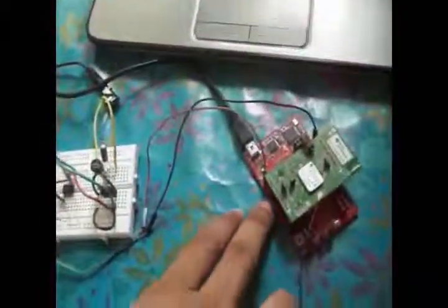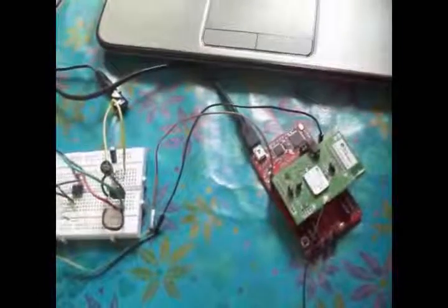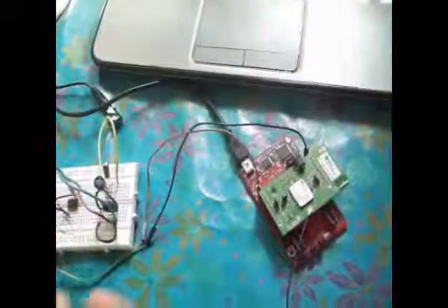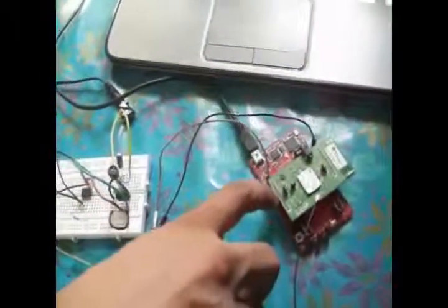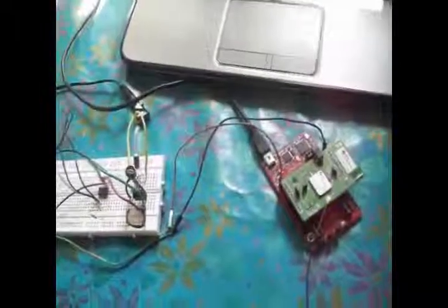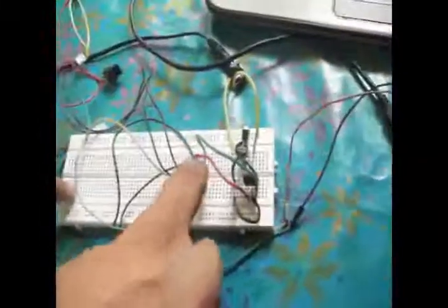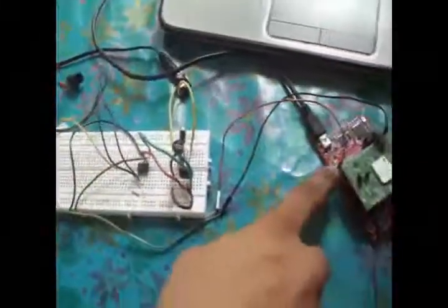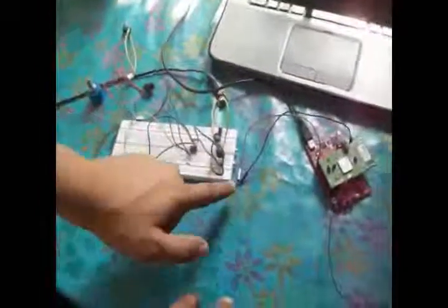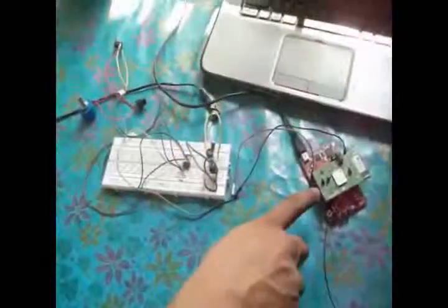This is the MSP FRAM board. We are taking in 2 channels right now. There are 2 more pins available, but to access them we will need to redesign the PCB layout, because they are right underneath the PCB. One of them is the output of the instrumentation op-amp, which goes there, and the second is the voltage across the resistor, which comes here.